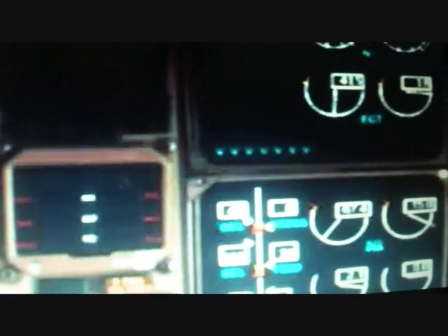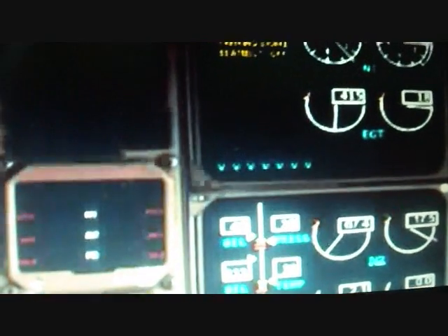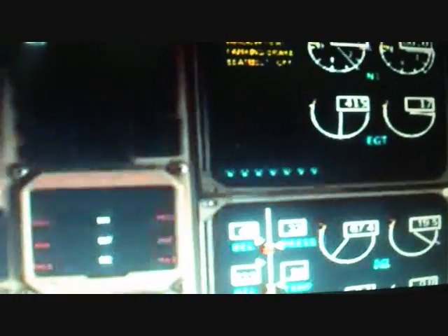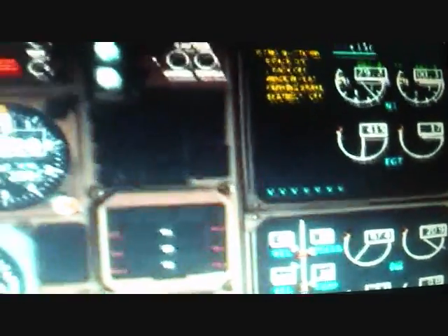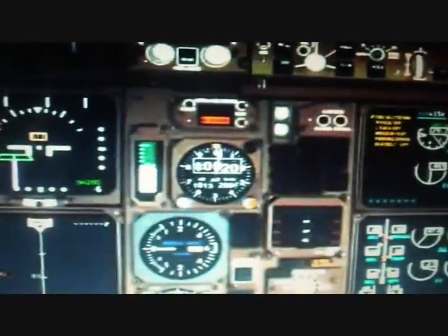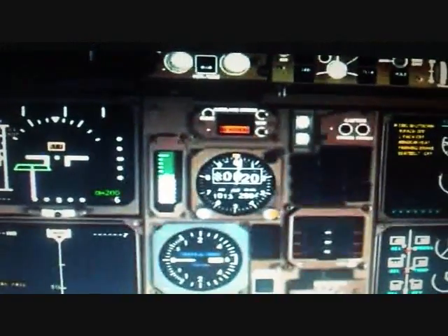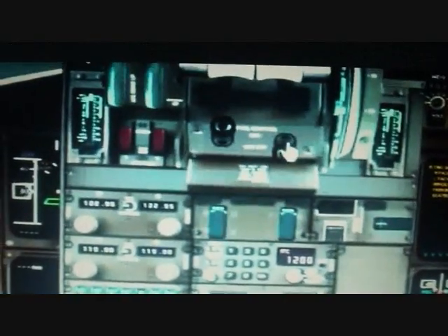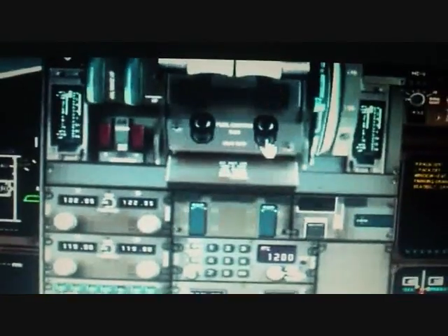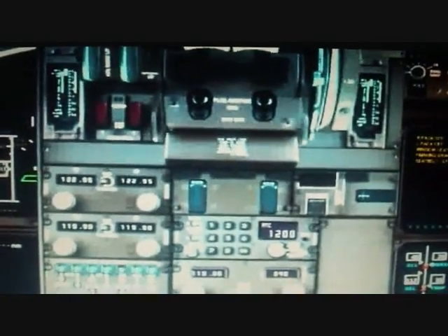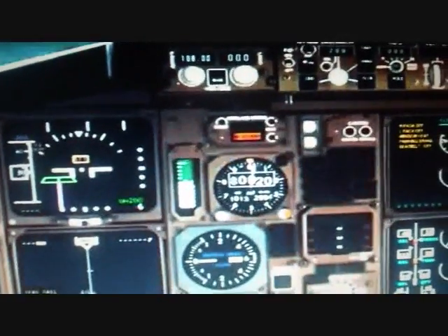And when you move the engine start switch to ground, remember, the valve opens, lets the air through to the starter turbine, spins the N2 compressor, and when N2 gets to 23%, open up the fuel valves. Now remember, 23% N2 is for the CF6 engine. The Rolls-Royce engine may be different.